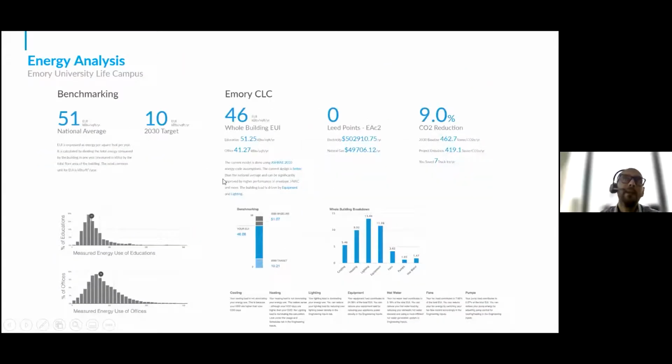effective. Similarly, once you have done the daylighting analysis, the next thing that we can do is propagate all that information about how much daylighting you are getting in the space to your energy models. What that means is, if you choose to provide sensors in the space, we know exactly how much daylighting we need to offset from the EUI, because that will lead to additional energy savings overall.